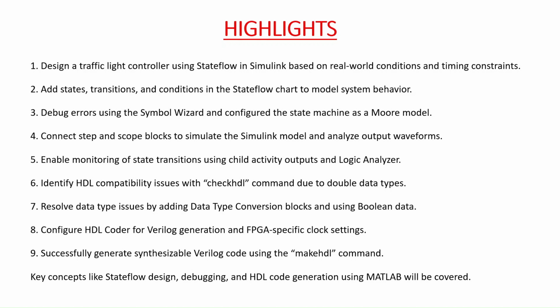First, we will design the traffic light controller using Stateflow in Simulink based on real world conditions and timing constraints. So we will make a Moore based FSM. We will add the states, transitions and the conditions in the Stateflow chart to model the system behavior. We will debug the errors using the symbol wizard and configure the state machine as a Moore model.